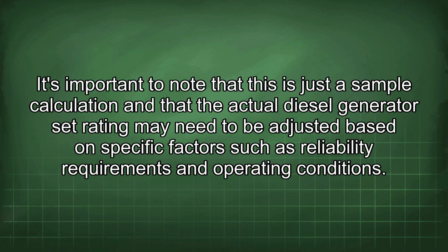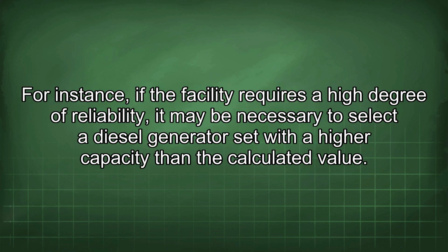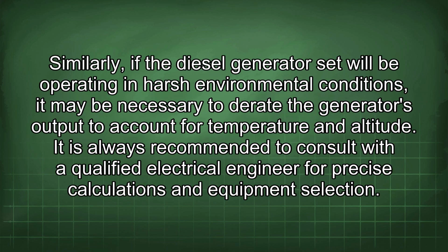It's important to note that this is just a sample calculation and that the actual diesel generator set rating may need to be adjusted based on specific factors such as reliability requirements and operating conditions. For instance, if the facility requires a high degree of reliability, it may be necessary to select a diesel generator set with a higher capacity than the calculated value. Similarly, if the diesel generator set will be operating in harsh environmental conditions, it may be necessary to derate the generator's output to account for temperature and altitude.